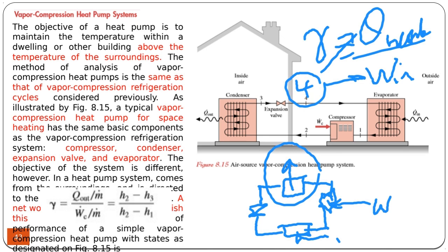But of course, their operation is dependent upon the external temperature, because if the outside temperature is very low, then they're not efficient anymore. They do not provide necessary heating. But under normal climate conditions such as Istanbul or Izmir, they can be easily used. But you cannot use them in, for instance, Erzurum, because the outside temperature is very low, meaning that it's not possible to absorb energy from the outside air.